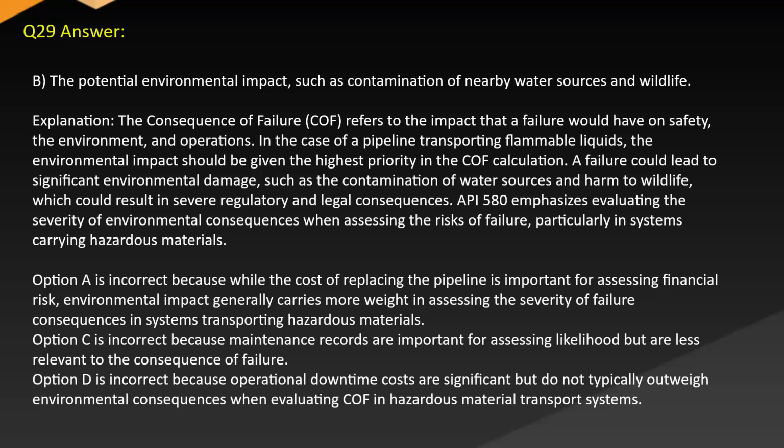operations. In the case of a pipeline transporting flammable liquids, the environmental impact should be given the highest priority in the COF calculation. A failure could lead to significant environmental damage, such as the contamination of water sources and harm to wildlife, which could result in severe regulatory and legal consequences. API 580 emphasizes evaluating the severity of environmental consequences when assessing the risks of failure, particularly in systems carrying hazardous